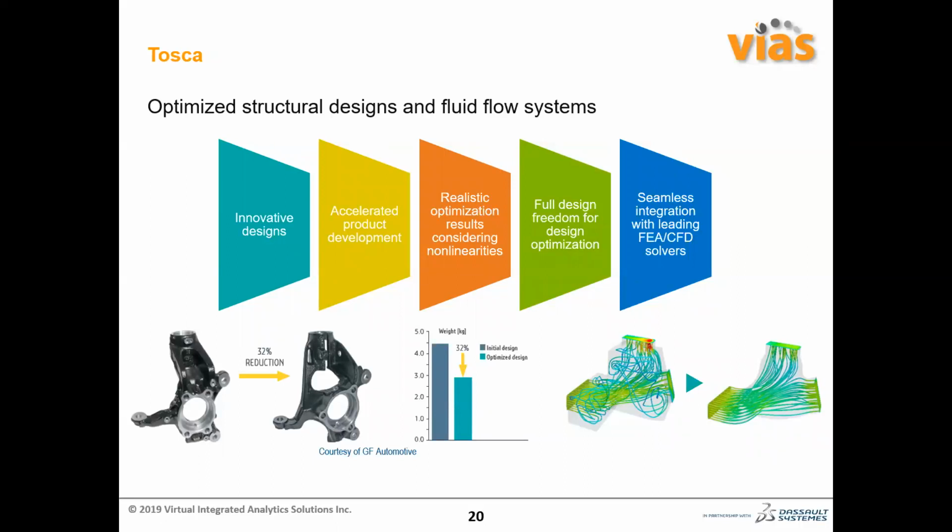By giving those manufacturing constraints, you can really get a part which will have the optimized design with minimum mass and optimum response. At the same time, that particular design can be manufactured by a particular kind of manufacturing process as well. And on a similar note, Tosca has a suite called Tosca Fluid, where you can optimize your fluid flow path as well.